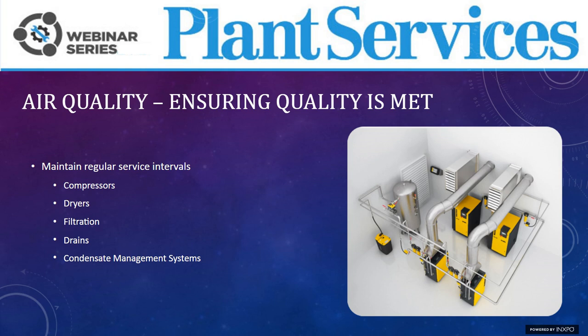Even after you've decided on what your air quality requirement is, there's a maintenance factor that you must consider. Equipment's typically in its best condition, hopefully that's the case, when it arrives to your facility. After the equipment's in operation, there's going to be wear and tear to consider. Heat load in the compressor room, moisture content in the air, dust and dirty environments, all of these can increase wear on your compressed air system.